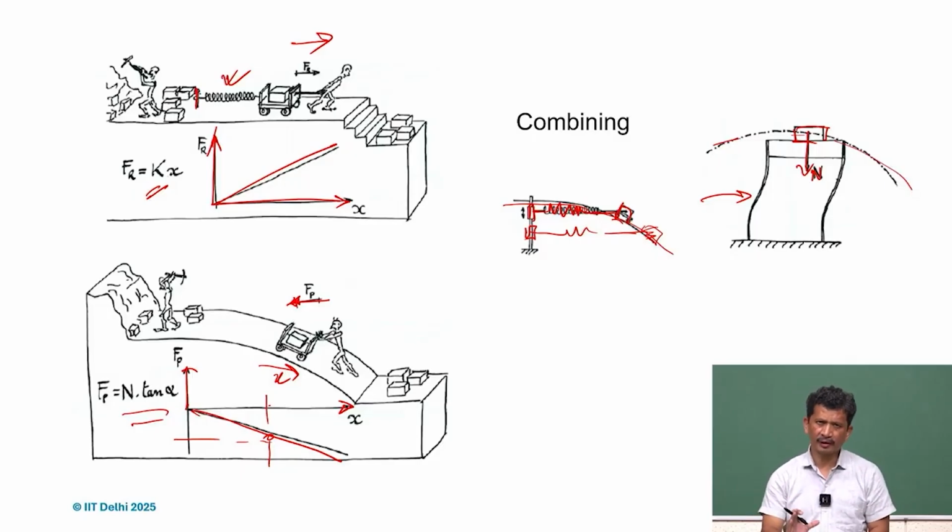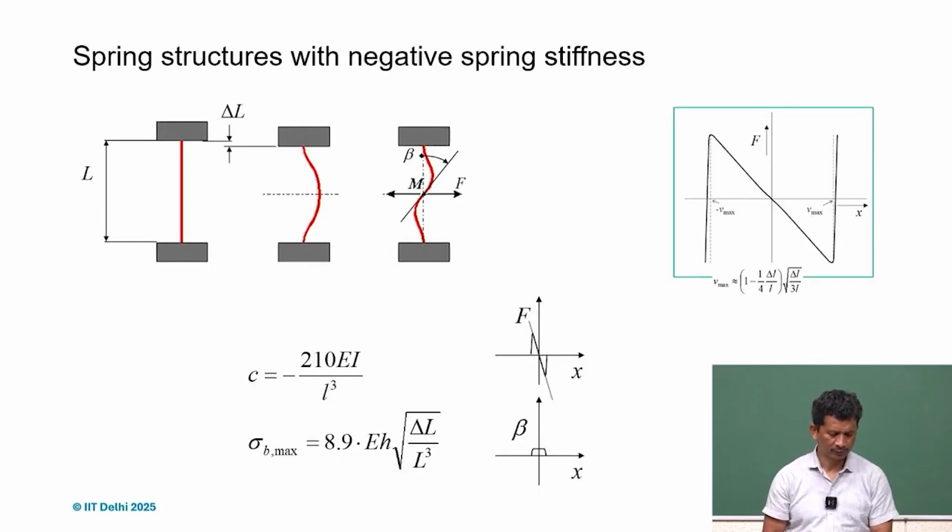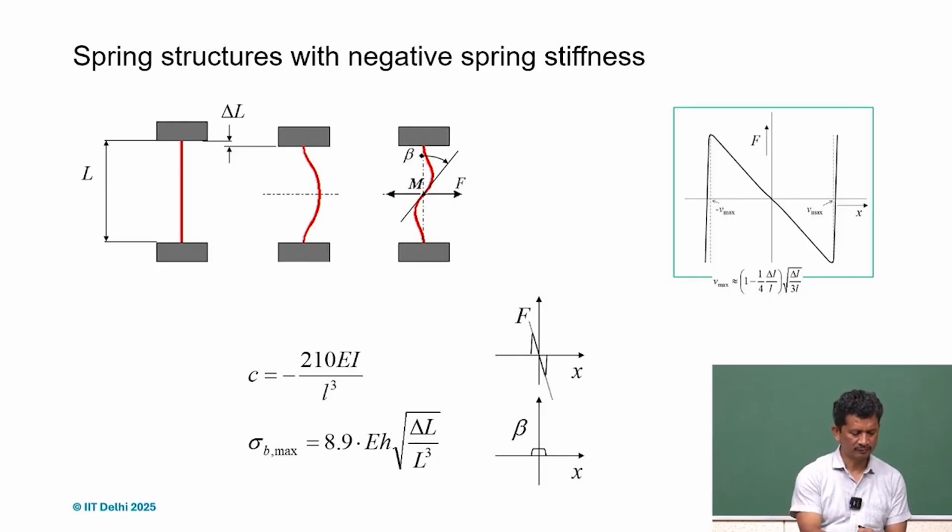So more or less, if that is the arrangement, what we realize is that parallel guidance with the negative force can give us some negative stiffness, and depending on this force n, we may be able to fine tune it and then achieve near zero stiffness. So in compliant mechanisms or in flexures, we realize that some of the things which are not desired can still be used, for instance in this case, the buckling.